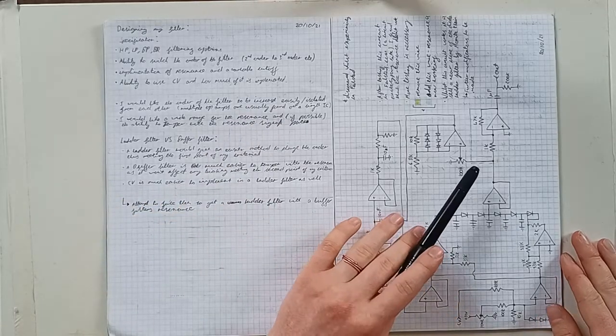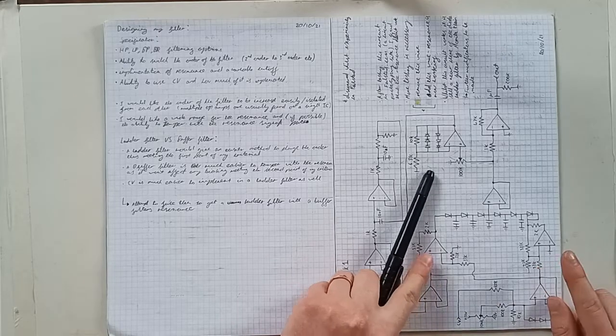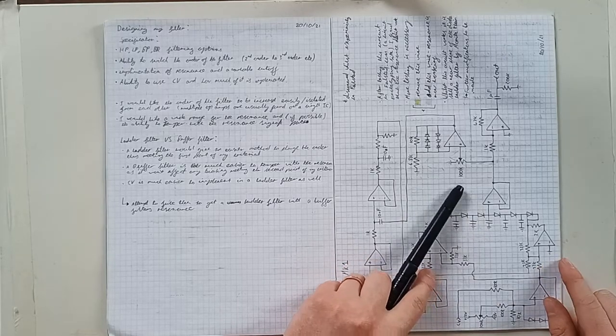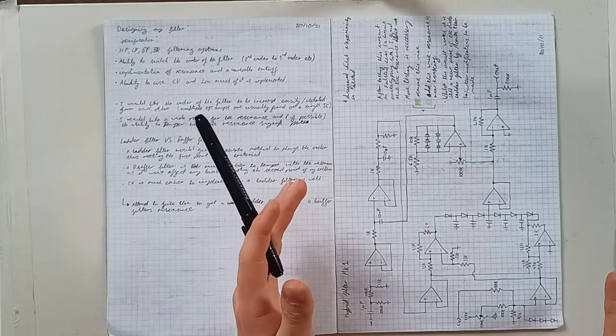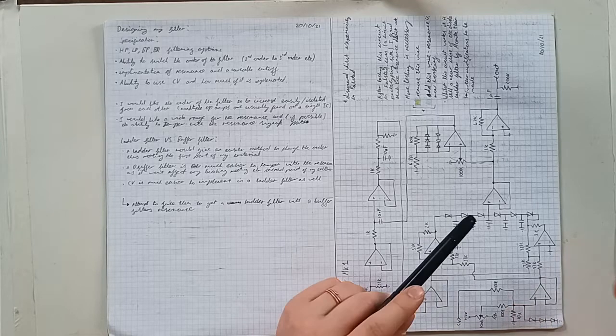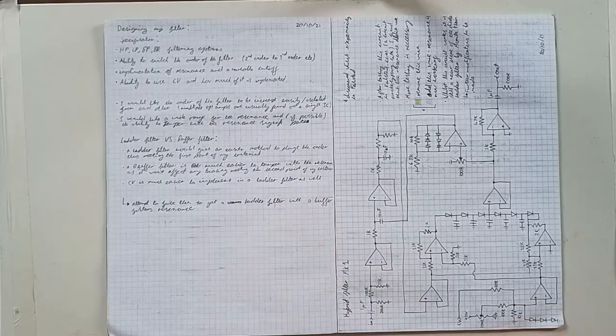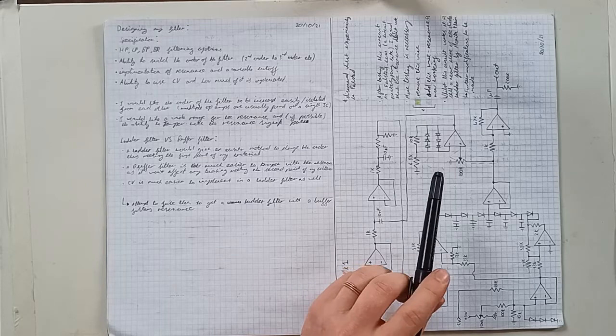And I realized the reason for that is because when you bias your input signal for the ladder filter, you also have to reduce the actual amplitude of it. Otherwise, you can risk clipping, and it's because of the curve of a diode that it produces when plotted against current and voltage.